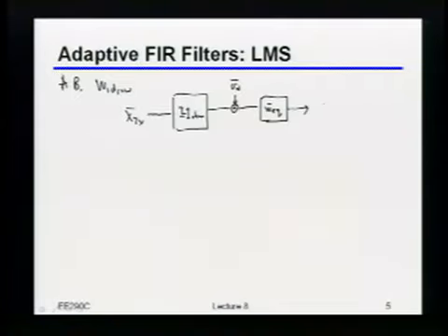After I've done all that, I'm going to do this whole operation to figure out what the analog received voltage is after this equalizer, at one particular sample point. Obviously, as you change the sample points, you'd fill in different values into this transmitted X over here, and that would give you different values for the final analog received voltage.